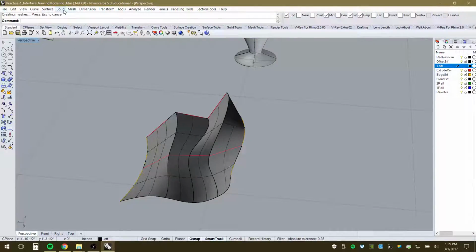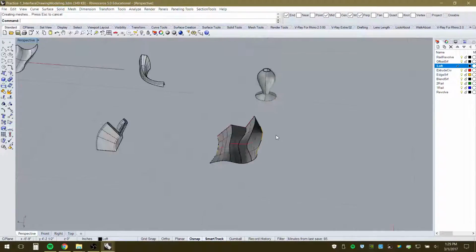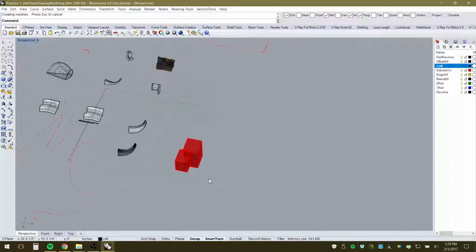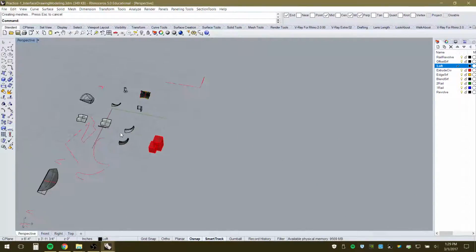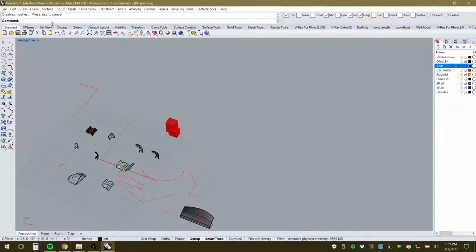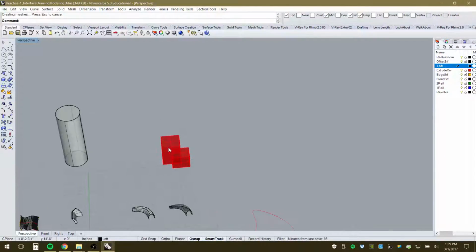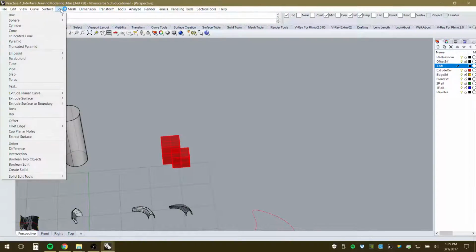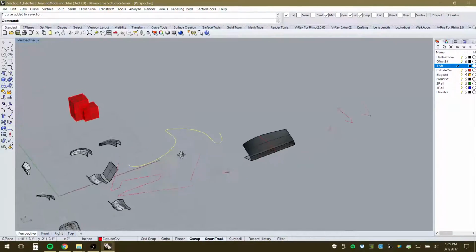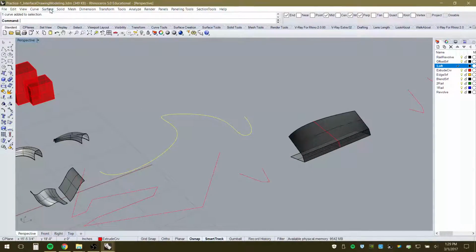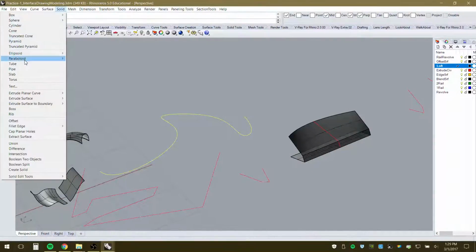Solids, again, it's mainly either boxes in terms of creating them. It's cylinders and boxes, so that is fairly straightforward. So I go into here, cylinder, it's going to ask me for a center point, obviously the base, radius, and then a height, right? Fairly straightforward. And you can create others here if you wanted to. Say I wanted to have a pipe along this overall surface, then you could select pipe.